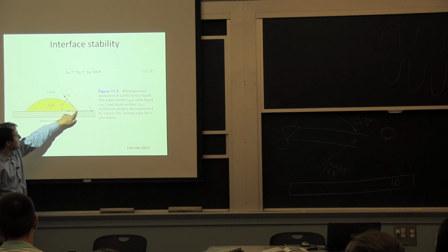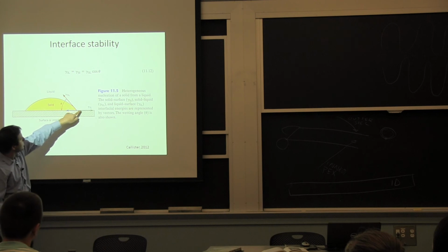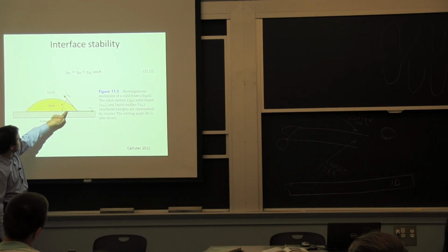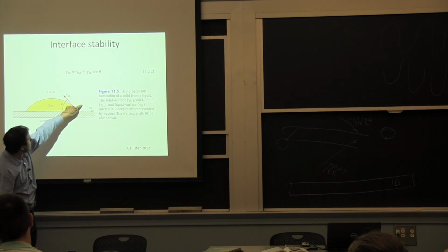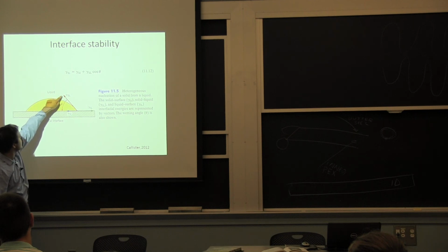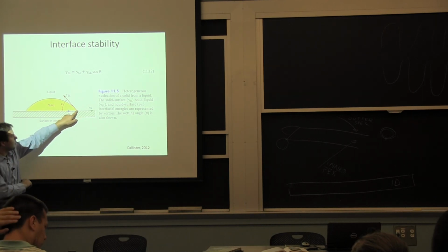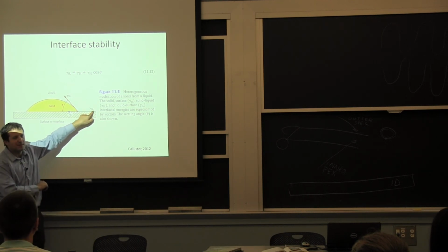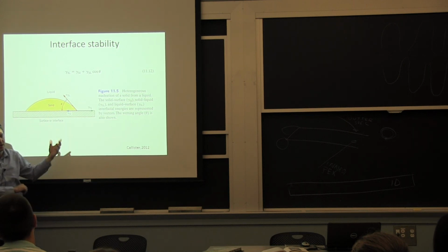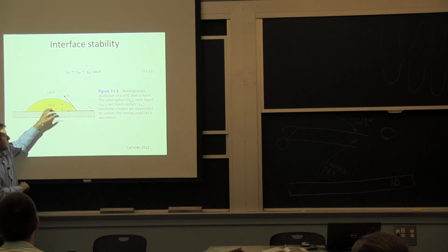So here we have a force equilibrium at that point here of the interface. So we're showing three vectors for the surface tension. It's the surface tension between the solid and, say, the mold, between the liquid and the mold, and then we have between the solid and the liquid. That's the red vector. So what happens is, at any point in time, this little corner should be in equilibrium, because if it isn't, it can just move so easily. It's already there. We're not talking about nucleating another element, another phase.